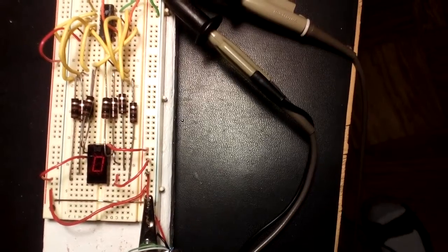This is the loop code, a little routine just to keep track of time, because I only change the display symbol every 2 seconds. Modulo 2 means even seconds. Sync signal for the oscilloscope. And this, we raise the enable pin to allow the data to reach the shift register, and this is the actual shift out instruction. This is all it takes really to put the numbers in the digits array out to the shift register. Okay, here we go.